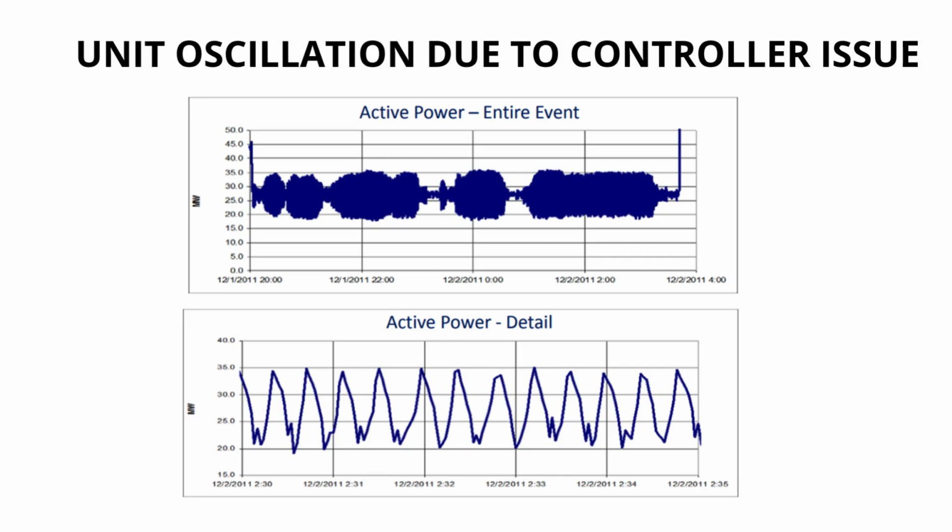That can definitely happen. Poorly tuned controllers on a generator, its exciter, its governor, maybe a poorly set power system stabilizer, PSS. Yeah, power system stabilizer. It's a device specifically designed to add damping via the excitation system. The slides don't detail it, but it's a key tool. Anyway, if these controllers are badly tuned, they can actually reduce damping or even create negative damping, making oscillations worse.